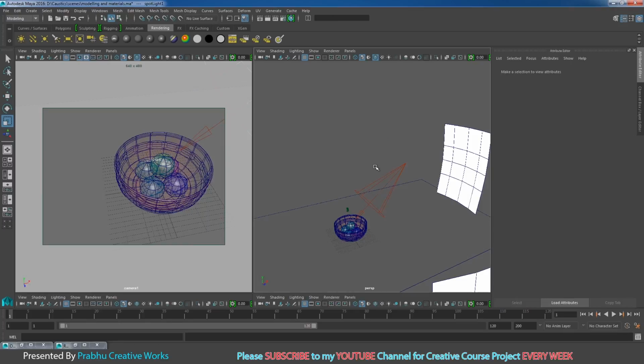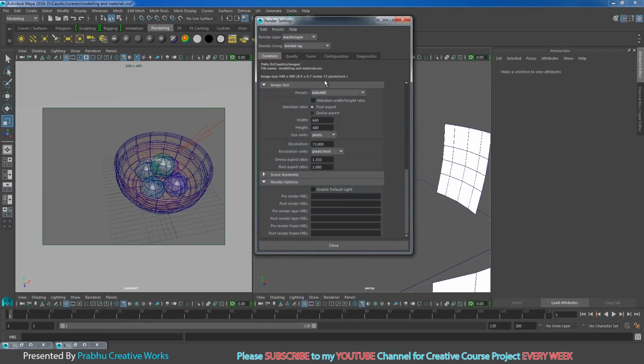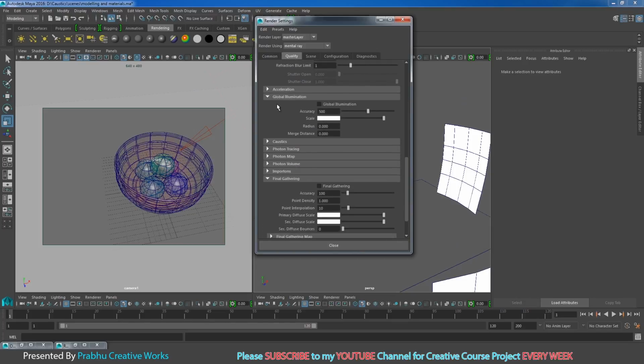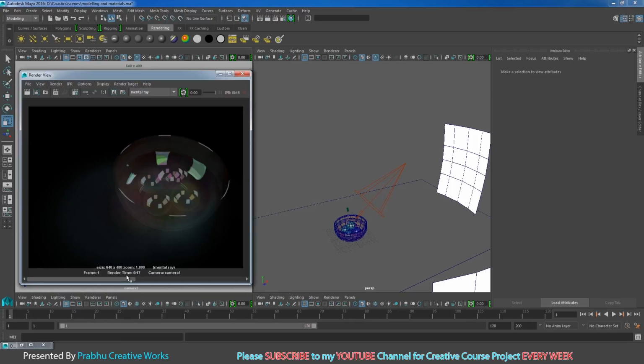So I will enable caustics on this light over here. You also need to enable caustics in render settings. Go to render settings and choose the quality tab. You definitely need to turn on show advanced options. Here we have legacy options. Go to the bottom side; under global illumination you have caustic options. I will enable my caustics. Then I will click on my camera view and click render. Now you see our caustic patterns are enabled.